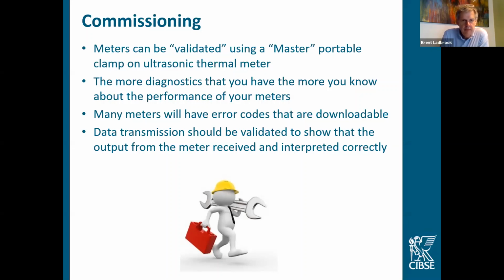I know I've been to validate existing thermal energy meters. It would cost more to validate it because you have to use a portable clamp-on type meter, clamp that on, and then on the day you go to do it, there's no air conditioning running. So it's reading 0. So the cost of doing this is huge.